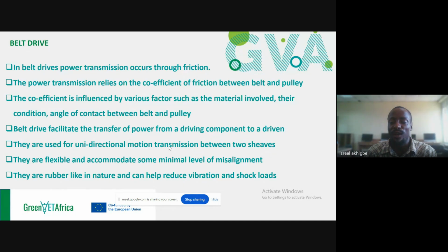Remember when you did your fittings course, we did the male and the female. The male was supposed to help us have the female receive the male. Similarly, that V groove is designed so that it will receive the V belt shape. Now, by friction, because the two of them have contact surface area, we're able to transmit motion. When the pulley is connected to our driver and the belt is on it, and it is in operation, the V belt will transmit motion to the driven or transmitting pulley.